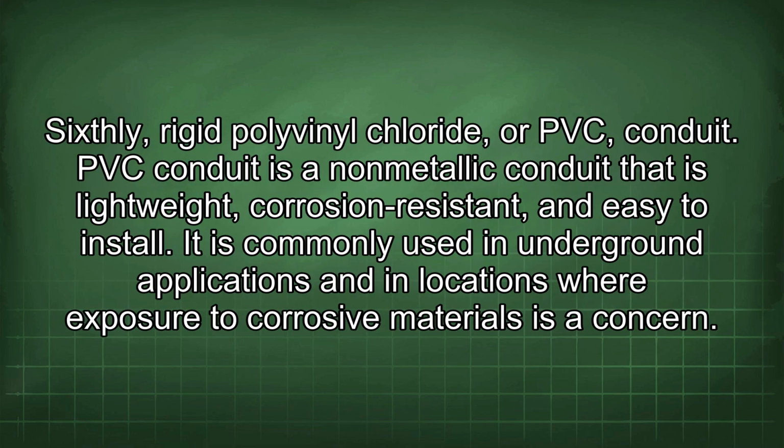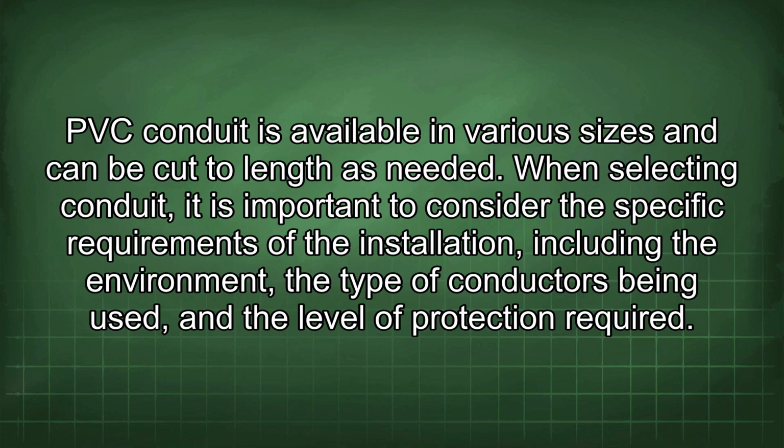Sixthly, rigid polyvinyl chloride, or PVC conduit. PVC conduit is a non-metallic conduit that is lightweight, corrosion-resistant, and easy to install. It is commonly used in underground applications and in locations where exposure to corrosive materials is a concern. PVC conduit is available in various sizes and can be cut to length as needed.